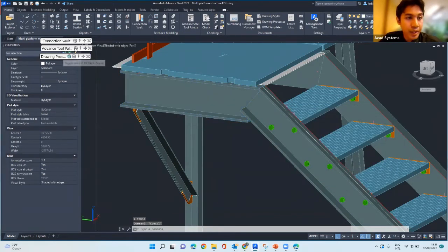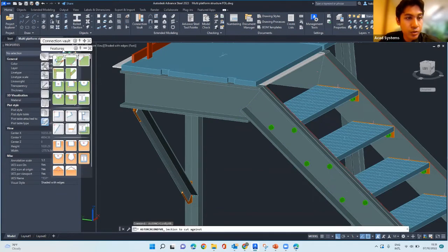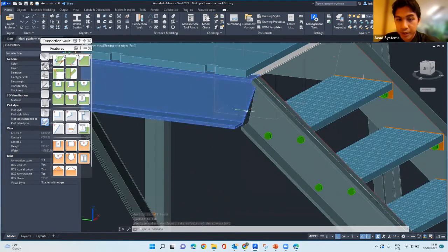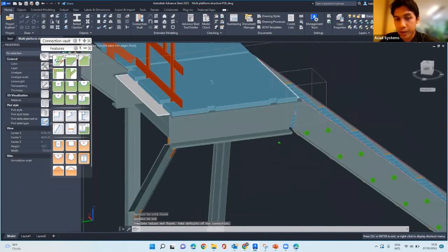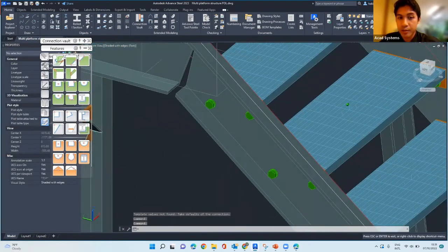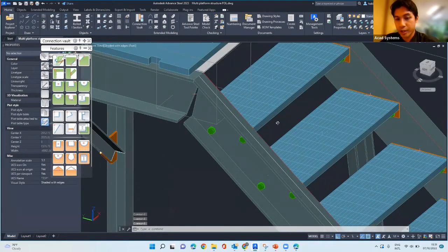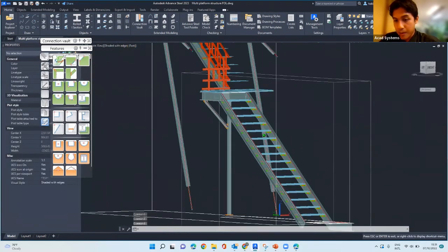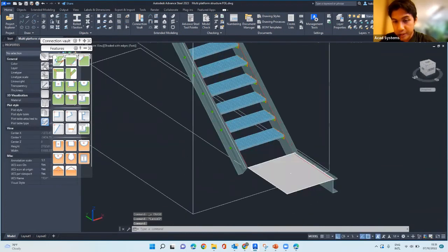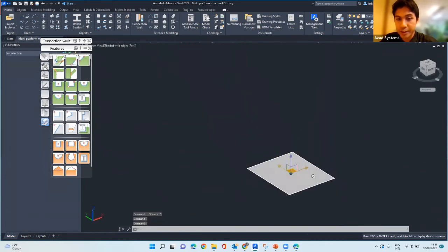Okay, and then you will apply the miter. Just go to that features and look for miter, click here, space, click here and space. Okay, then it gives you a miter, it gives you the connection. If you match up the beam size, it will be mitered nicely. Sorry. It's probably because of the settings I also set for the bottom landing just now.